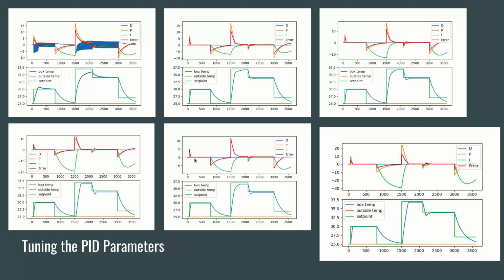These next three are where we varied the P and the I terms, both to try and tune the controller as well as for stability analysis. And in doing this, we found that our KC term really can be any positive term and doesn't appear to ever really be unstable just due to the limitations of the system. And then here we can see our final tuned parameters with a quick rise time, almost no overshoot.